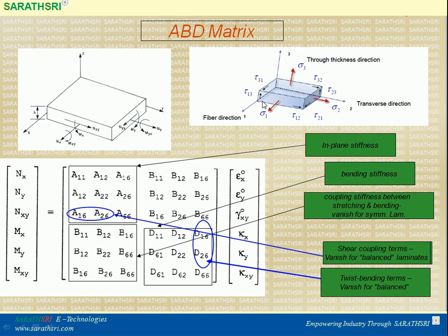Similarly, the shear stress field tau 12 acts in the 1-2 plane, with the corresponding complementary shear tau 21, so tau 12 equals tau 21. That's why a total of 6 stress components are involved in any three-dimensional loading.